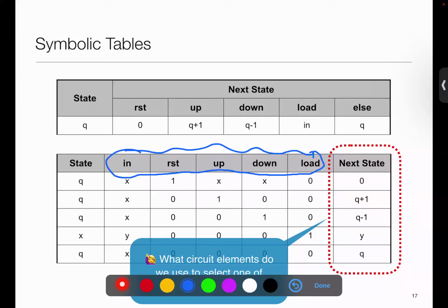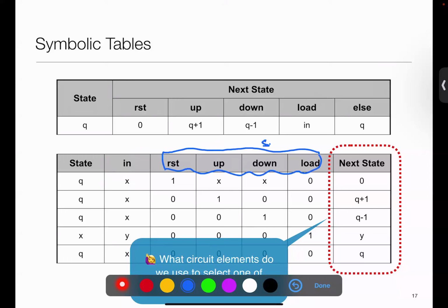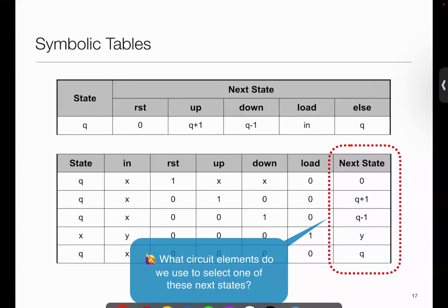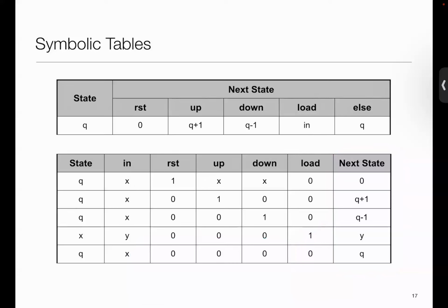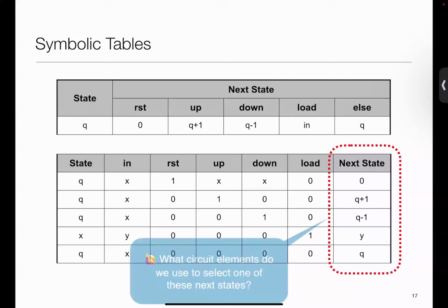Whose select bits are being driven by, not in, apologies. So whose is going to be driven by this. This feeds into select of mux. And this reminds us of mux. So that would be a way to kind of design it. So this is what it looks like. I can create a multiplexer. Now, the thing is, looking at that, we had 5 cases. 5 is a little bit ugly because I have to go to 8-to-1 mux. So what if I could do it in 4-to-1 mux? So that's what the slide does.